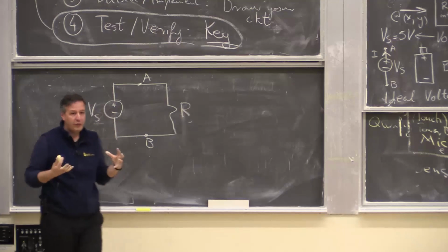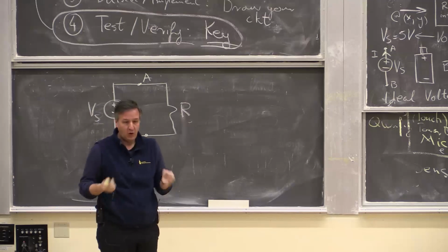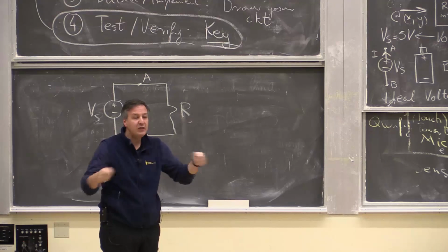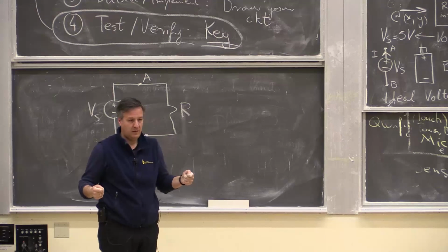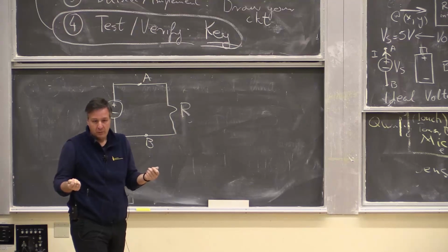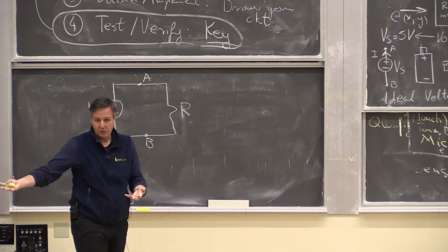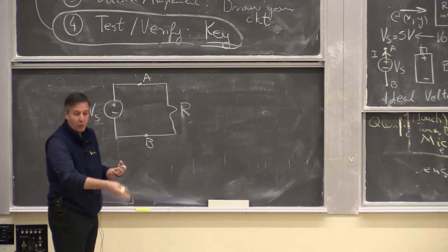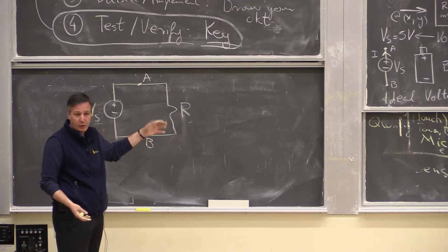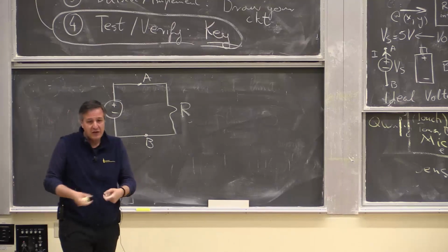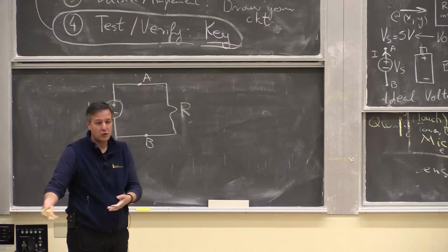When you're confused by how the circuit looks, always try to find where the nodes are, and just draw all the circuit elements between these nodes. We'll be doing that a little bit just so you can get the feel, because that's exactly how computers go and solve things in the end. We'll be showing you the more formal framework based on what Babak was showing on the flows and graphs. But sometimes circuit designers don't have the patience to do all this, so they take shortcuts.